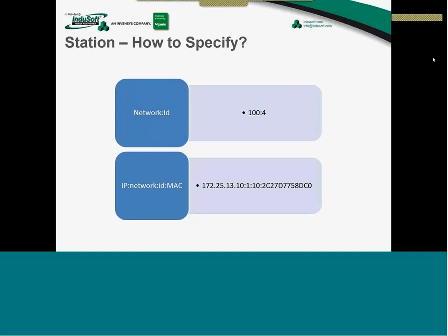The format is network:device. This information you in general get from the device data sheet. Or you in general have a way to access the device by web and set these configurations, or access that information using some configuration software. And this is a standard for BACnet.